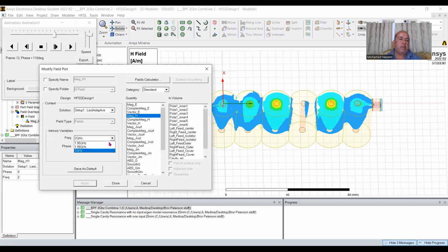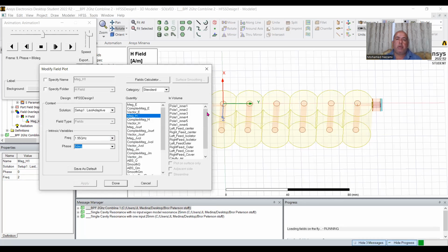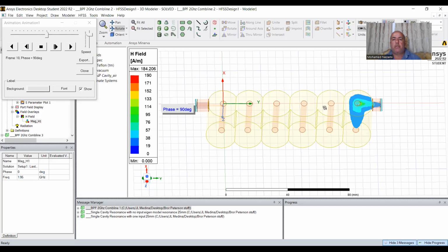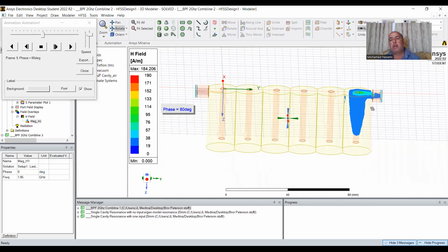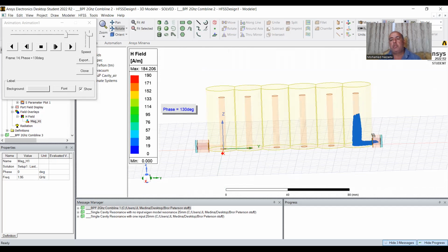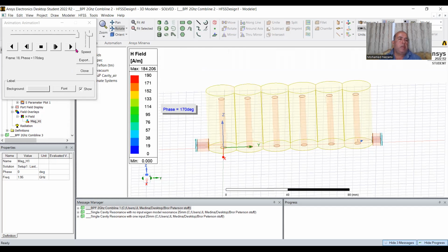So we need to go to another frequency. Okay, there we go. That's probably 1.95. Okay, there you go. That's at the cutoff frequency. You can see that the signal comes in and never makes it. In fact, you can see that the E field is not even getting to the top where it should be. It's basically getting sucked into the ground.